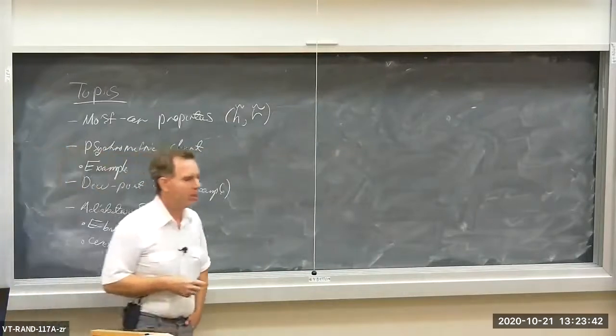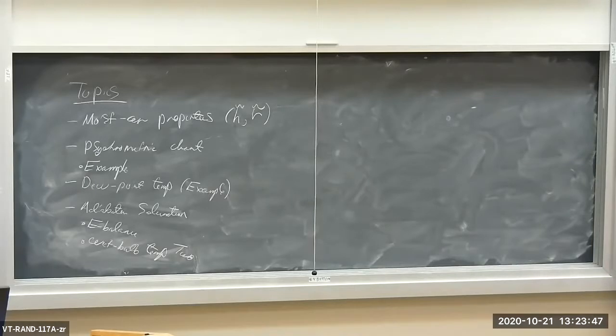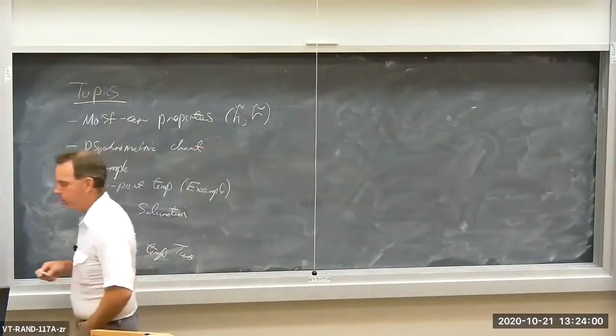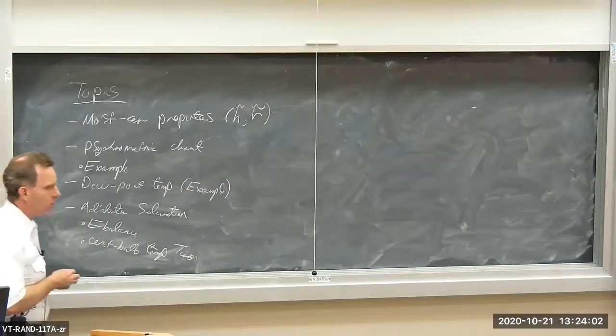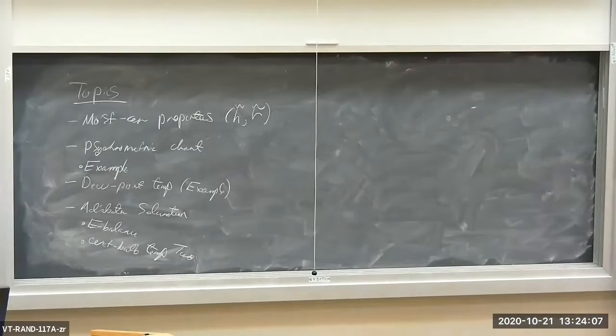The psychrometric chart basically takes most of the grunt work out of doing these psychrometric problems that you're going to be introduced to here. So we're going to do an example involving evaluation of properties using the psychrometric chart for some moist air. We're then going to be moving on to dew point temperature. What's the dew point temperature? You've all seen dew out on the grass in the drill field, or dew or condensate dripping off of a cold window or a cold surface in a room.